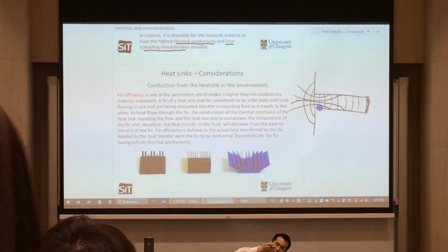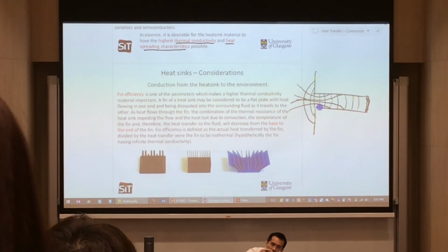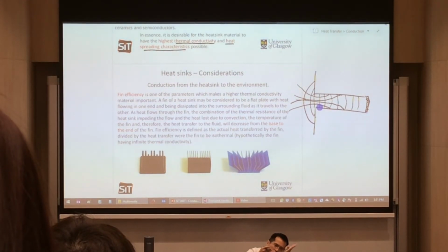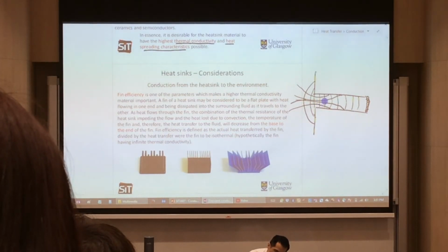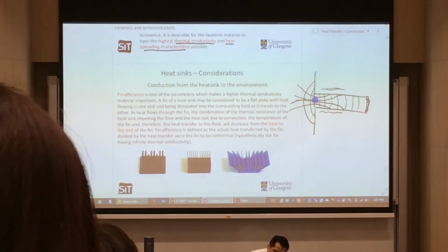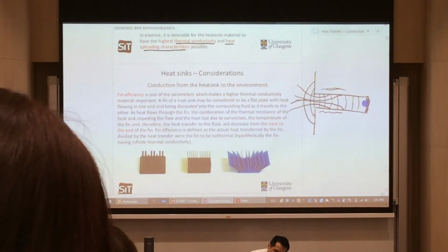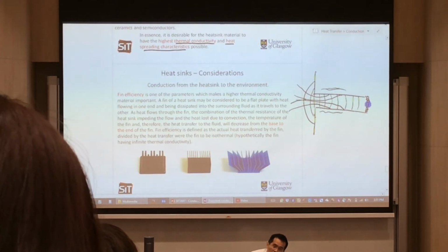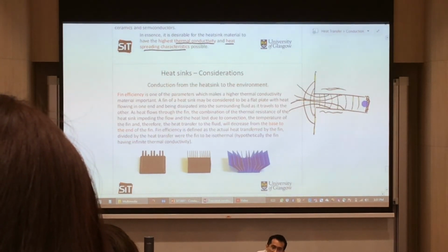compared to the other parts of the fins. That's because the heat that's flowing out is going to diffuse to where it's nearest to the ambient. It's not going to make its way all the way to the end of the tip. It will try to get cooled down somewhere over here because that's the nearest part for cooling. And that means the temperature within that cooling fin is not going to be constant. If it were constant, that would be an ideal cooling fin.